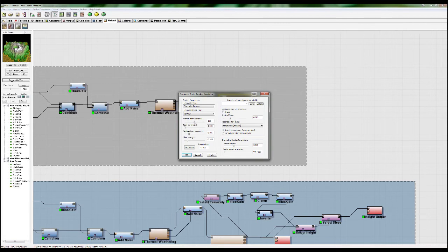We're going to crank the base duration up, as we want as much erosion as we can in this, and we'll just tweak the rock hardness to be not too solid. Basically, rock hardness sets, if it's at 1, you'll pretty much get 0 erosion. And the sediment carry is how much of the rock is actually eroded away and carried down the mountain. That will happen with large torrents of water. Will, for instance, carry away more of the soil and sediment that gets eroded away. So we're going to set this rather high. We'll bring this down. Filter strength, we're not using filter, so we don't have to worry about that.